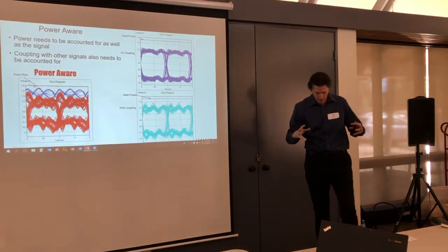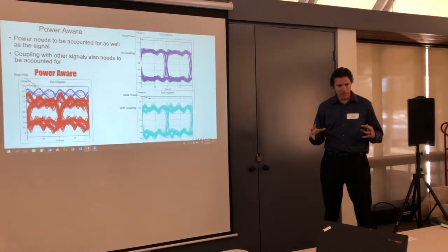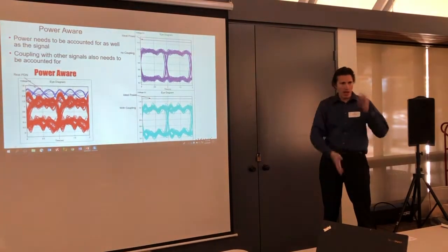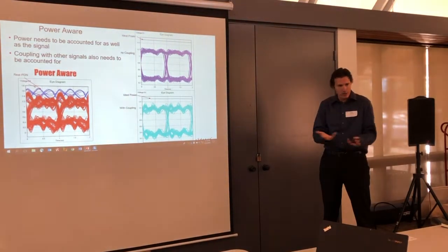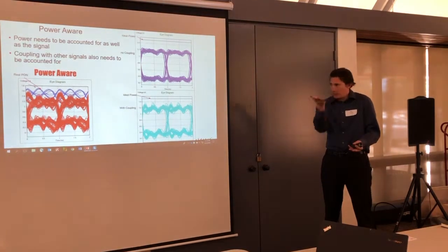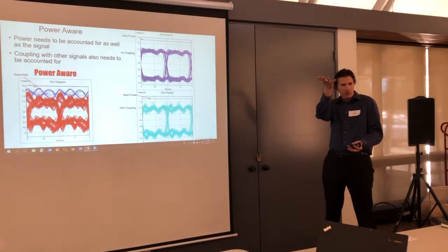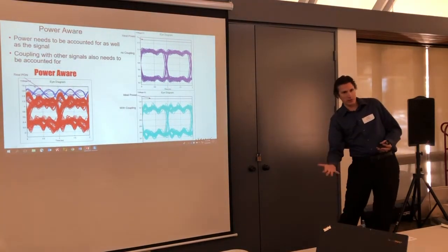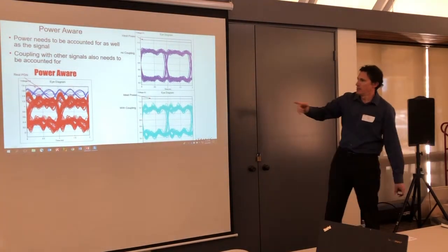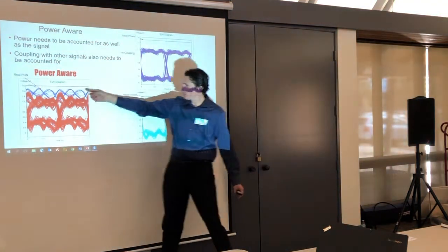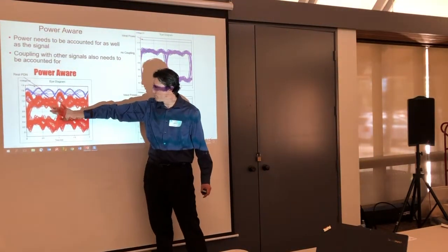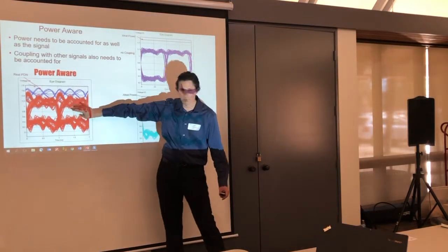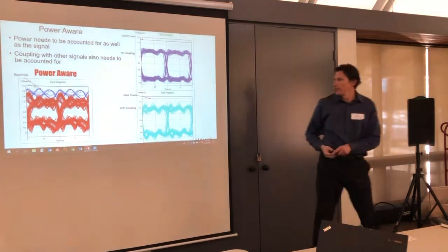Like if you imagine a large IC or a memory device, and all of a sudden it's rapidly switching on, off, on, off, on, off. The power underneath that device is going to be fluctuating a little bit around 1.5 volts. As the device tries to switch on, it's going to draw a bunch of current, so the power level is going to go down. When it turns off, it's going to bounce back up. And so those fluctuations in power also mess with the eye diagram. You can see this clean power supply, wide open eye; noisy power supply, the eye starts to close.